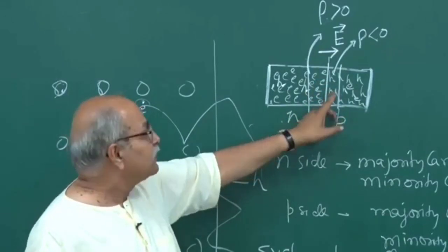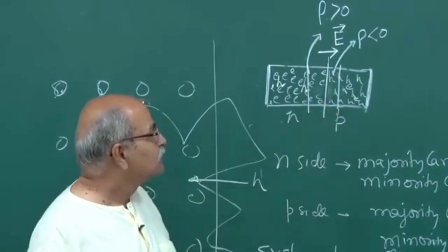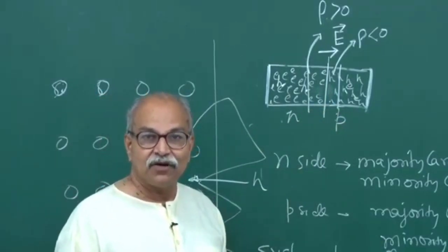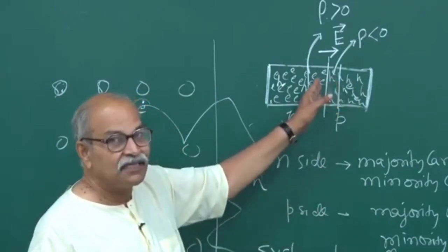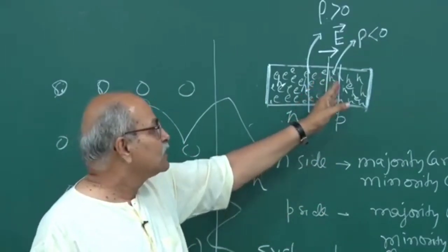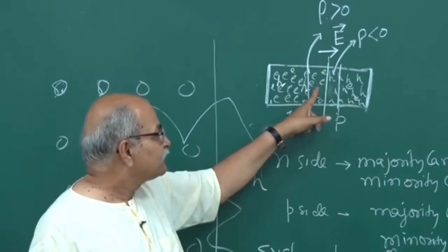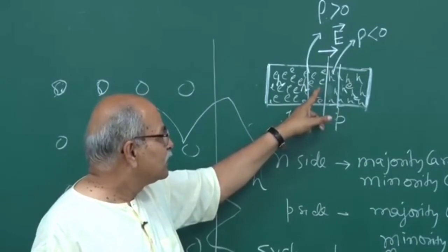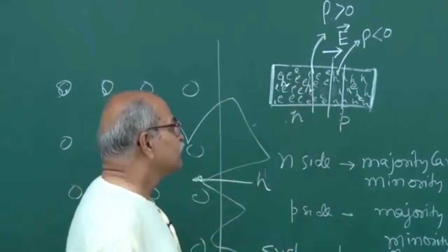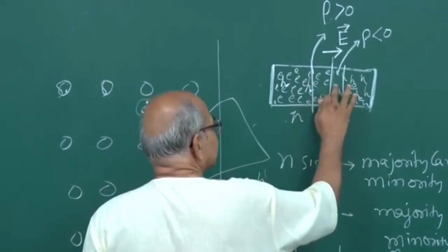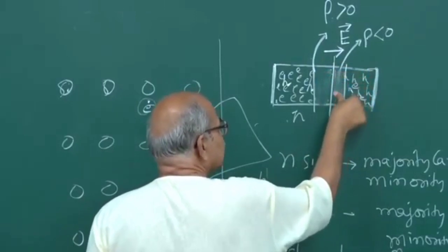What will happen? Suppose this electron meets this hole, it fills this hole. So now there is no hole and there is no conduction electron, that pair is gone. Similar thing will happen everywhere. Holes which are coming to this side will also combine with the electron. Holes coming from this side means a bond is broken from here, and this hole comes and fills that, then a hole is created here, so this electron goes from here to here, this broken bond is filled by this electron, and this hole has come to this side, and then this electron has filled that hole, so that is also over. In that same fashion, you will have no charge carriers left.